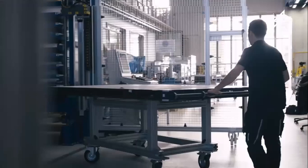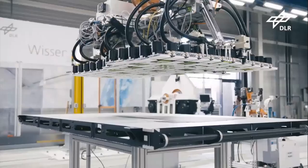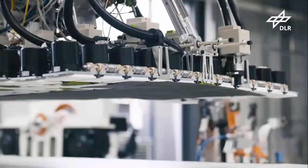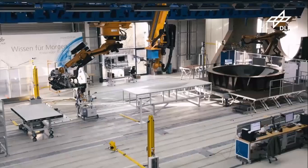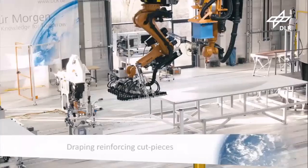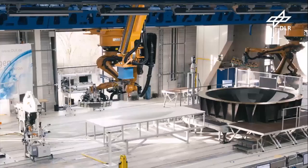The modular gripper recognizes the shape and the exact position of the cut piece. The patch is autonomously approached by the gripper, picked by its 127 suction modules and transferred towards the tool. On the way, the modules are transformed into the target geometry of the placing position. The determined holding forces of the modules and the adjusted surface ensure the desired draping of the cut piece.